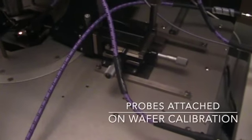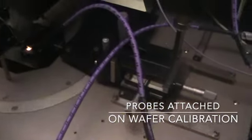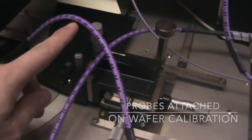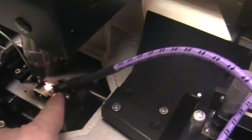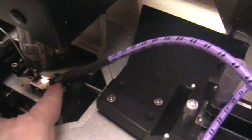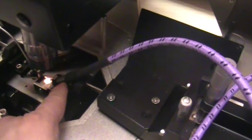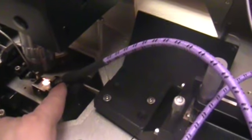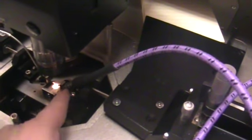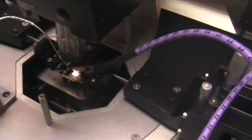After all of the mechanical calibrations have been completed, it's time to hook the cables up to the probes. In the case of port 2, we're using a shorter 1.5 foot long Gore cable that goes from port 2 directly down to the port 2 set of probes. I have a set of Pico probes on here right now, 50 gigahertz GSG 100Ps. And I also have very good luck with Infinity probes, I-50 GSG 100s and I-50 GSG 150s.